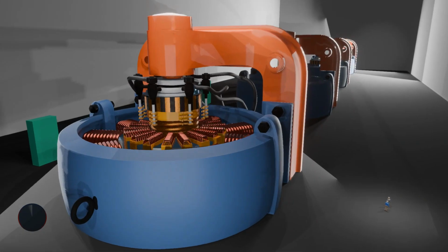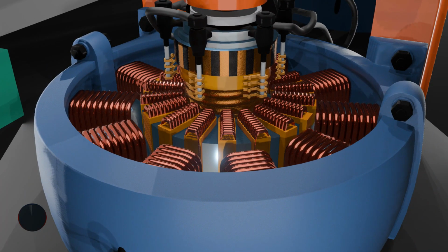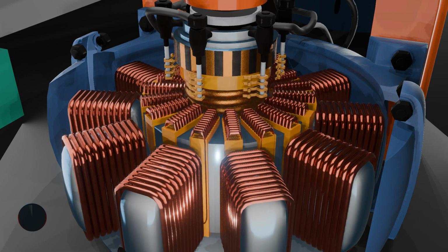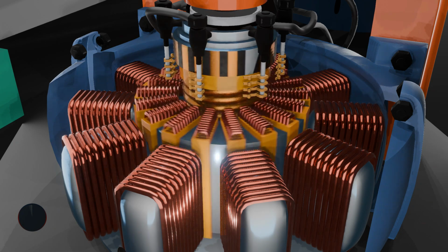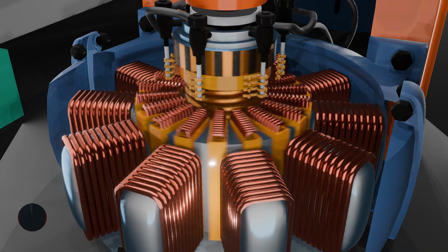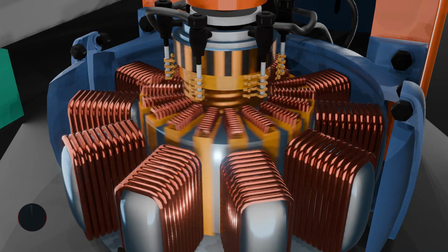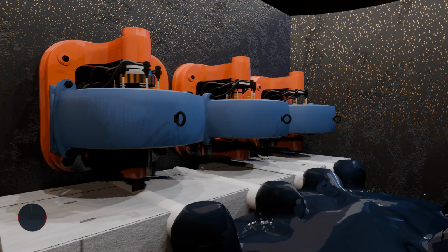Finally, in terms of the generator design, sometimes the generator might be made of magnets, or it can be wound with some set of copper wire which will be further connected to an exciter. Again, the aim is to achieve the relative movement between a magnetic field and the conductor windings. Hence the reason why electricity is generated as the turbine begins to rotate and turn the generator rotor when water begins to flow through the blade of the turbine.